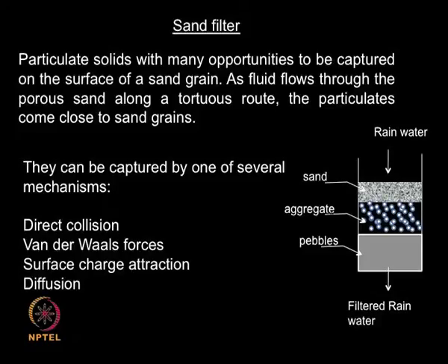So how do they get captured? There is direct collision between the particles or waste material and the sand or pebbles present. There could be van der Waals forces, there could be surface charge based attraction, there could be diffusion and so on. So different types of interactions take place as the fluid moves through this depth filter, and the solids in the fluid get captured or removed.